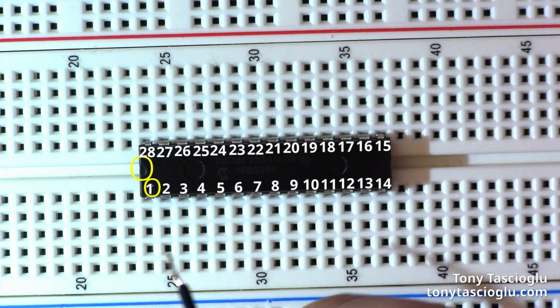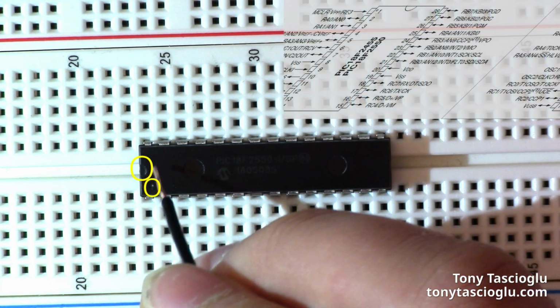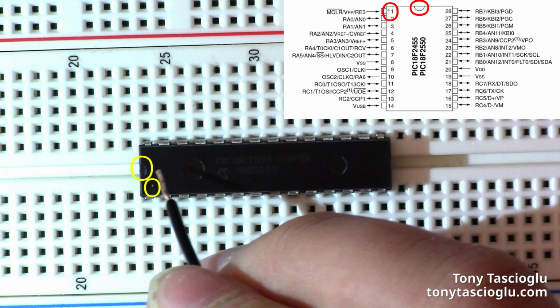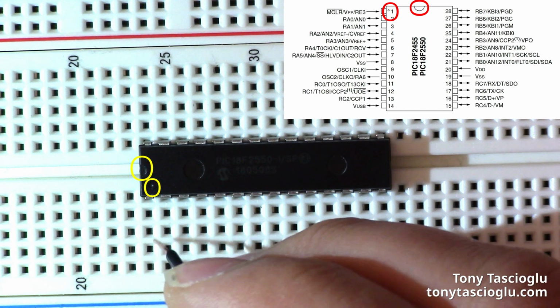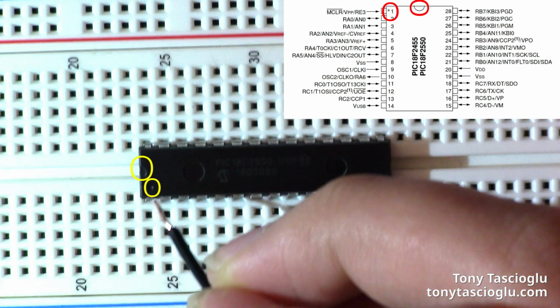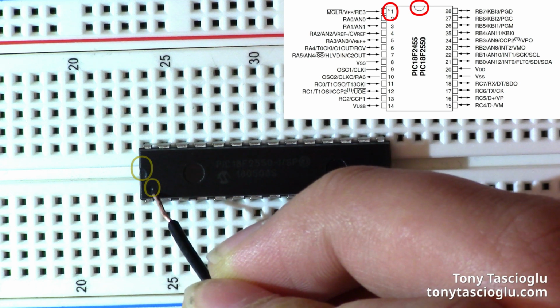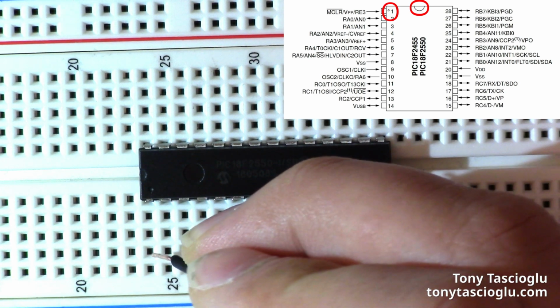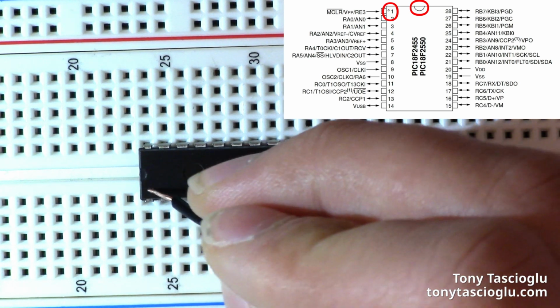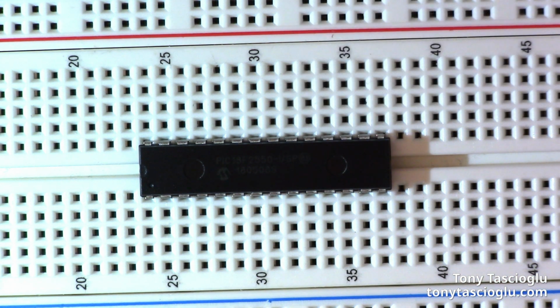Now, to indicate this, there are 2 little notches. So the first one is there's this notch over here. This indicates the start and end pins. So pin 1 is here, pin 28 is here. And then to indicate which one is pin 1, there's this tiny little circle here embossed into the chip. That circle indicates that this is pin 1. Both of these notches also exist on the datasheet, so you can use that as a reference.